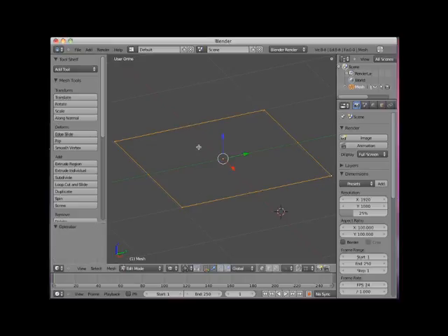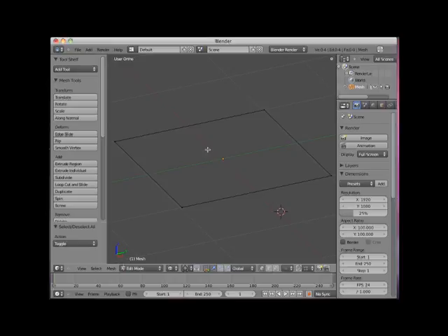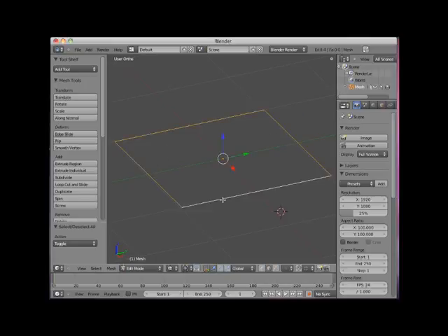deselect the vertices, and then press Ctrl-Tab and select Edge Select Mode. I will select the four edges and press the F key to recreate the plane's face. I will now select the top and bottom edge and press the Subdivide button. Note that the two edges are divided in half and that there is a new edge from the midpoint of the top edge to the midpoint of the bottom edge.